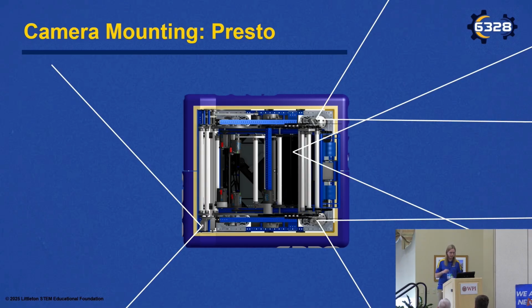Also, an important warning here, we're talking about maximizing the total field of view of the vision system, but we should be careful when talking about individual cameras. It's typically a bad idea to go with cameras that are wider than about 100 degrees. The standard camera model, which is called the fisheye model, breaks down above about 100 degrees with really wide-angle lenses, so pose accuracy will tend to be really poor with those. In general, just running multiple cameras that are getting close to 90, 100 degrees tends to work much better than a single very wide-angle camera.